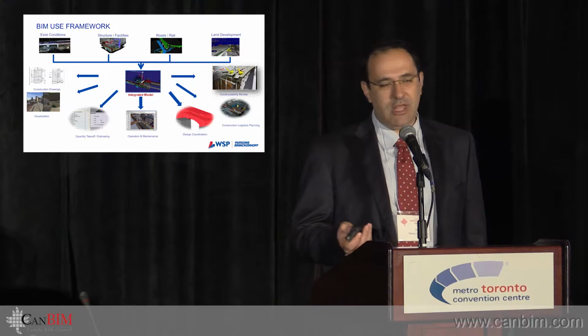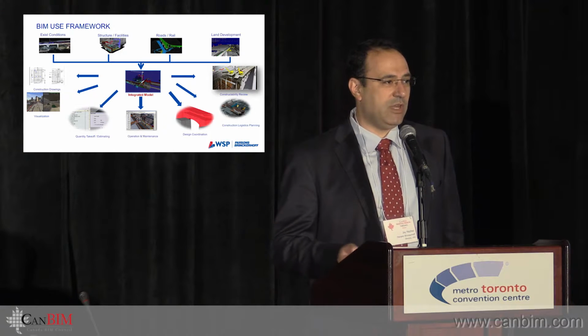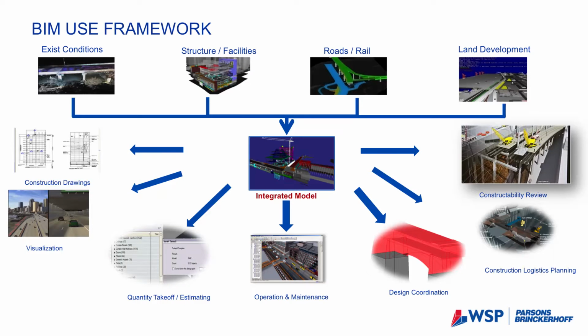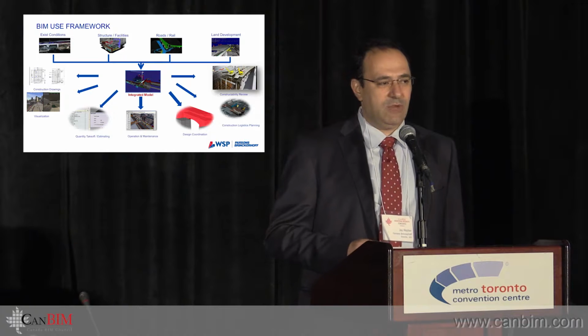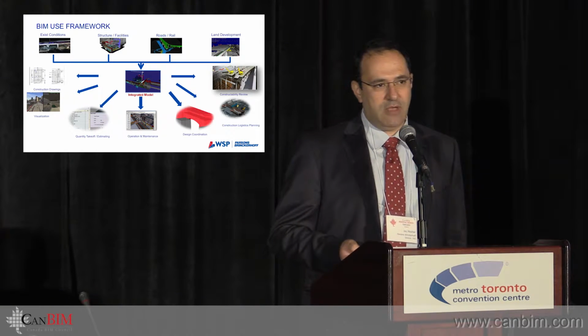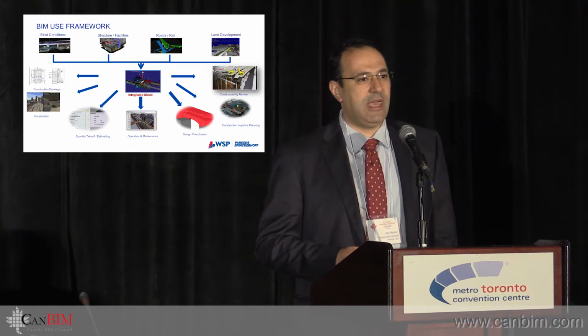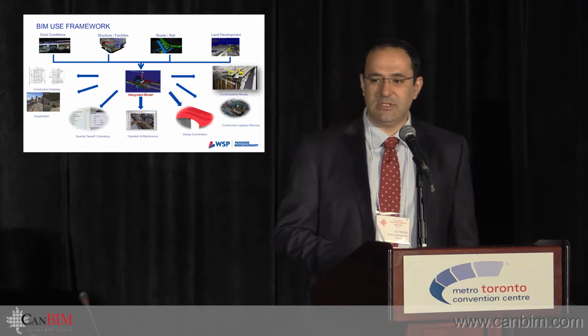What we focus on a lot is just how do we integrate all these different models into one integrated model that's going to give me my construction drawings, that's going to help me with visualization, quantity takeoff, design coordination, and then during the construction phase, constructability 4D, 5D. And one of the most important things that we're seeing right now in the industry is clients requiring that these models be linked to their asset management and their operation and maintenance systems.